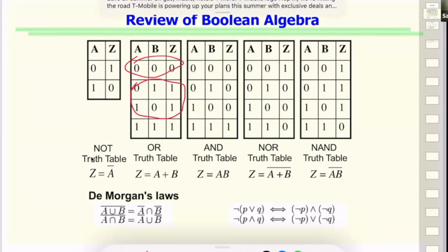So AND is where the output will not be high unless both of the inputs are high. So the output has direct relations. As long as at least one of the inputs is low, the output will be 0. Now you have to see these two tables are taking into account only 2 inputs, but they can be 3, 4, n inputs.